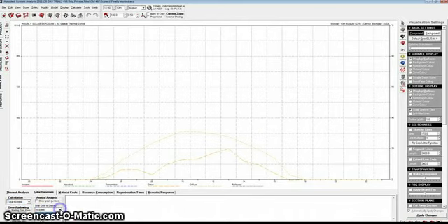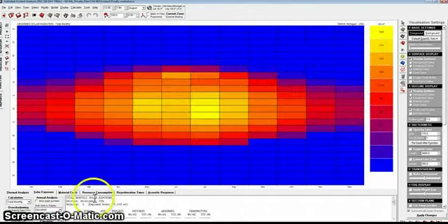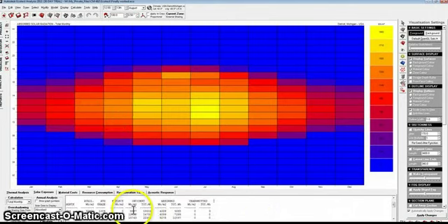So we're going to do the absorption. You go down to the bottom and click calculate, and there's a graphic right here that shows all the hours of the day and the months of which has the most solar absorption, and it'll also give you numbers and how much energy the building absorbs. Scroll down to totals, and you can see the totals right here. We'll go back up and look at the absorption totals, and here's the absorption totals right there.